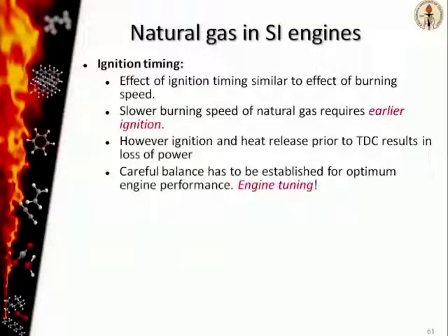So the solution to this is that you have to carefully balance the spark timing and the injection timing so that you can get the optimum engine performance when you convert the engine to operate from gasoline to natural gas. And so the main thing here is tuning of the engine once you have all the other components in place.